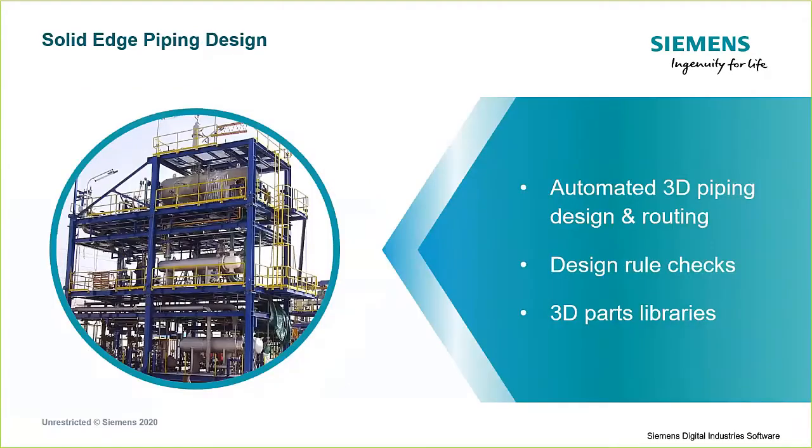Next, we have the piping design. This allows us to see in 3D layout just how things will look when we go and build them. Piping design reads the intelligent data from P&ID using that data exchange link, and then the components are placed and the pipelines are routed. To route the piping, you simply draw the path from point A to point B.